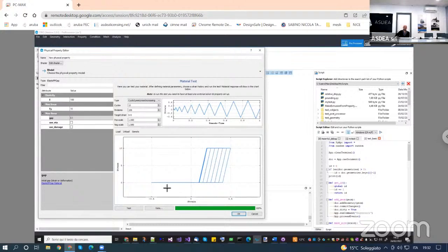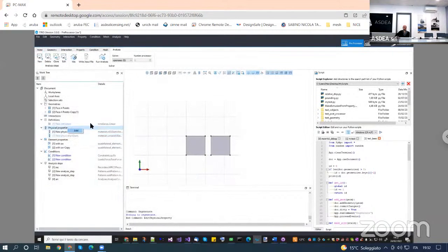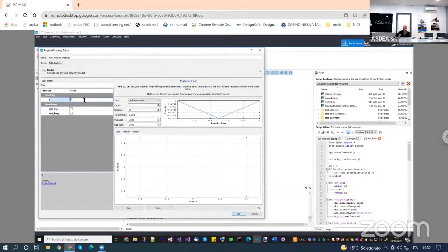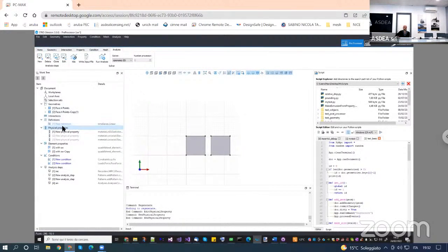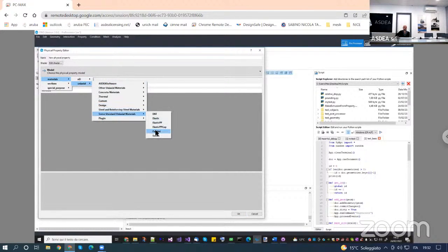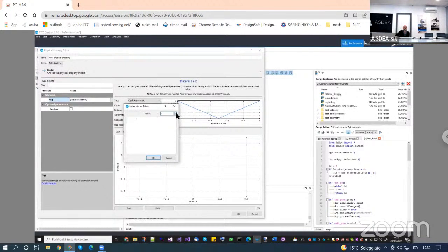Okay, so this is fine, but you can see it doesn't happen in the other direction. Now imagine you do this one. Then you create another material, which is elastic. Let's see how it works. Some standard elastic, and let's give it a small strain hardening, like 1000 initial stiffness, let's say 10. And then you can place them in parallel. Let's see what happened. Material, uniaxial, some standard, parallel. And then you put 2. So you want the gap material and the strain hardening. The factors would be 1 and 1.